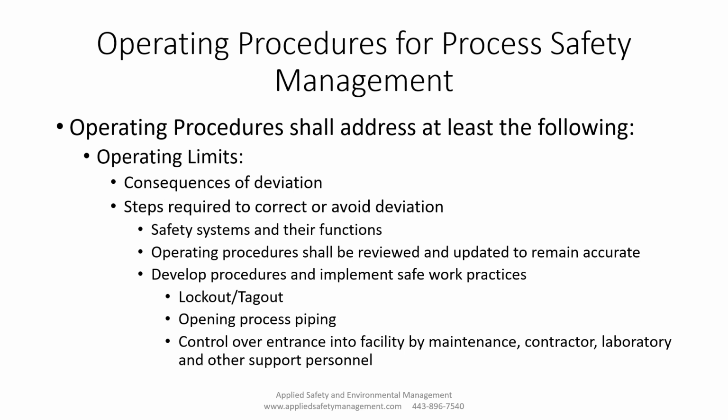The employer also has to have control over the entrance into the facility by maintenance, contractor, lab personnel, and other support personnel too. We just don't want people wandering in anywhere. We want people to be trained not just on the process, but also on the hazards. Then we don't have a person who happens to say, "I'll just cut through," and they end up with a chemical on their foot or on their hand, and they don't know what to do. So we want anybody going in there to know exactly what these chemicals can do and the first aid procedures, to make sure they're going to be as safe as possible.